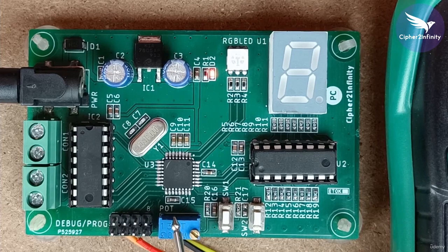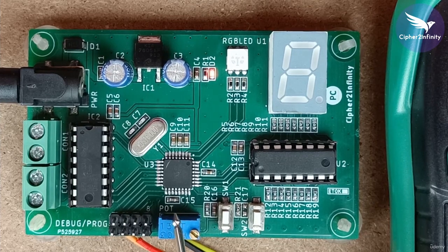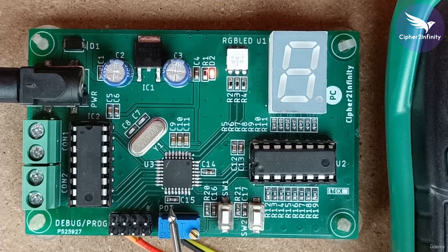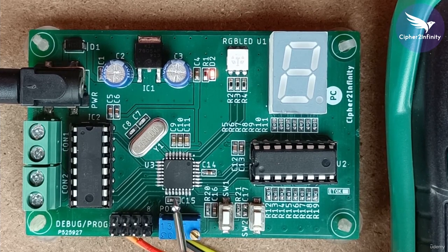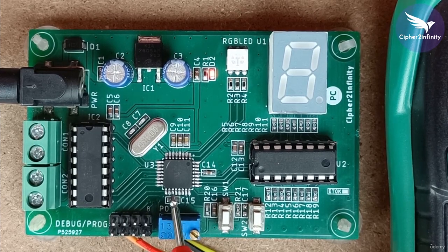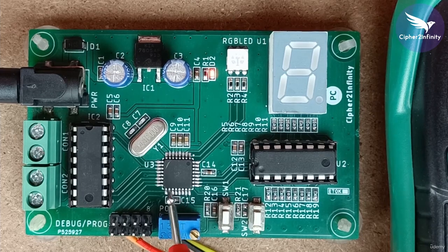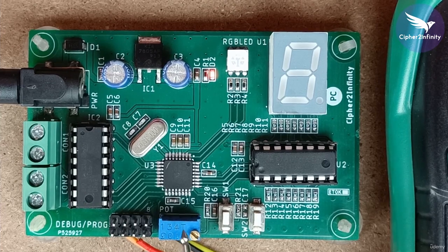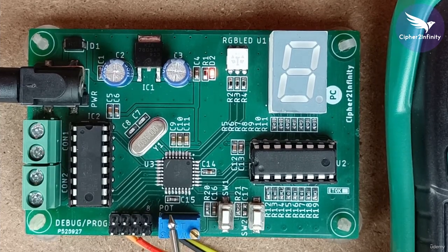Okay, then the second point is, if you are not getting the voltage on the center point, then it might happen that the center point is connected to the ground pin. So you have to physically check the PCB, or do a visual inspection, to see whether it's connected to the ground by mistake or not. Because that could be the reason why you will get 0 volt on the center point, or why you will not get the expected reading on the center point.